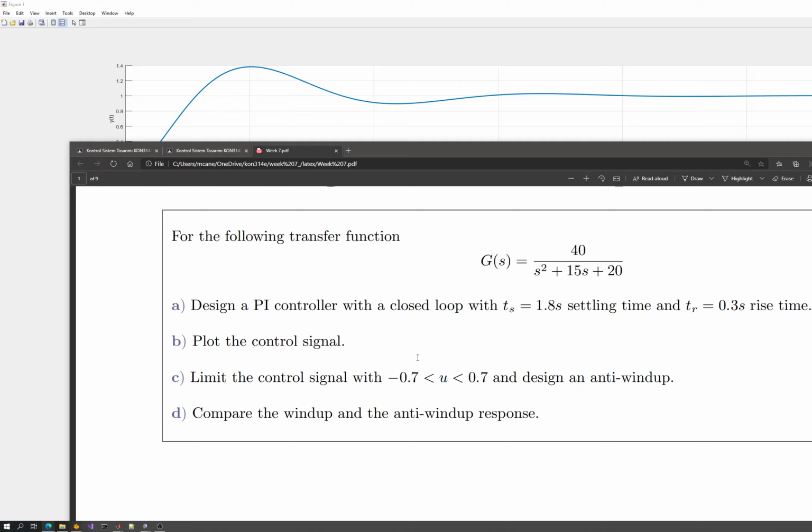So one way is to use Simulink, and that's the easy way. You might go ahead and open Simulink, stop this video and try to implement this. You know what the controller parameters are, you know the system, you place them, and between F(s) and G(s) you can place a saturation element. If you double click that saturation element, you are able to set a lower bound and an upper bound. So just type in these values in a feedback structure, you can apply a step, and then you will see the true output and everything will be alright. But here we will try to implement this using only code, and therefore we might use a little bit of control theory and some coding tactics.